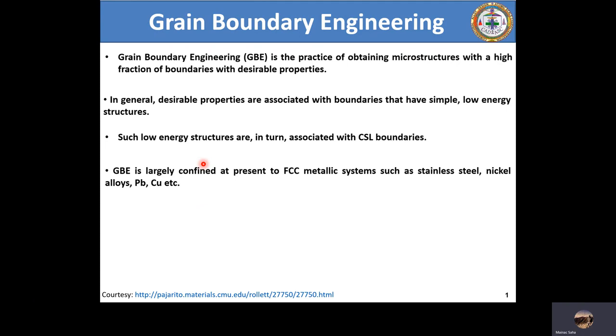Again, it has one plane and atomic stacking, where the ideal atomic stacking sequence should be ABC, ABC, ABC, and so on. But definitely, in the case of aluminum, the problem is that the stacking fault energy is very, very high, so the chances of twinning during plastic deformation are much lesser as compared to those FCC metallic materials which have low stacking fault energy.